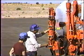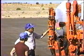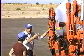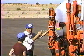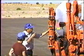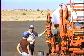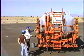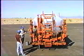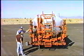Okay, we've circulated the spray bar, we're going back into the tank. Now we're going to assume that we already know how to set up the pump, and we already know how to regulate things as far as spread rate. In the cab we have pre-selected the width of the spray bar that we're going to turn on, and we're ready to go because the spray bar is circulating now, everything is hot, we're ready to spread asphalt.